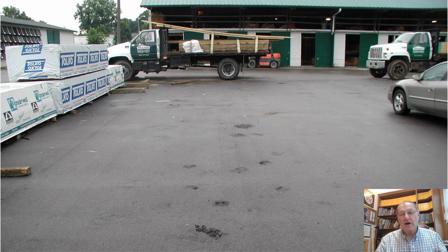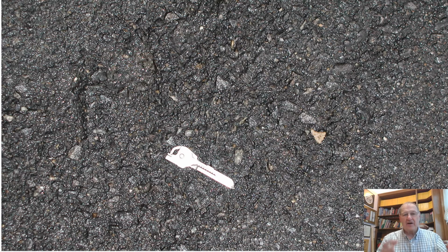And the issue was that all these tearing marks come from that forklift right back there. And so you get all these marks and divots, and as you can see, there's very little rock in this mixture. It's mostly composed of sand, which is a weak aggregate skeleton.